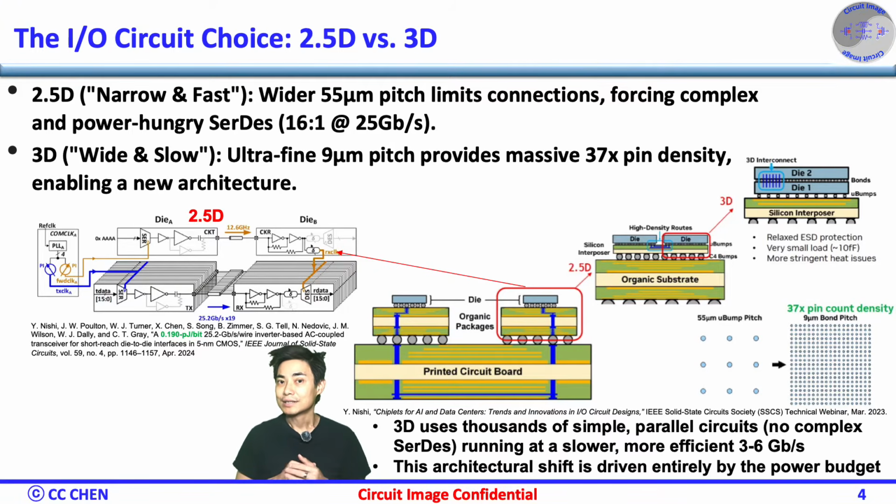Power delivery intertwines with thermals. A 3D stack is a skyscraper whose PDN must carry K times the current through the limited vertical TSVs, creating IR drop, so upper dies see lower, noisier supply rails, and the real killer is electromigration, whose rate accelerates with high current density and temperature.